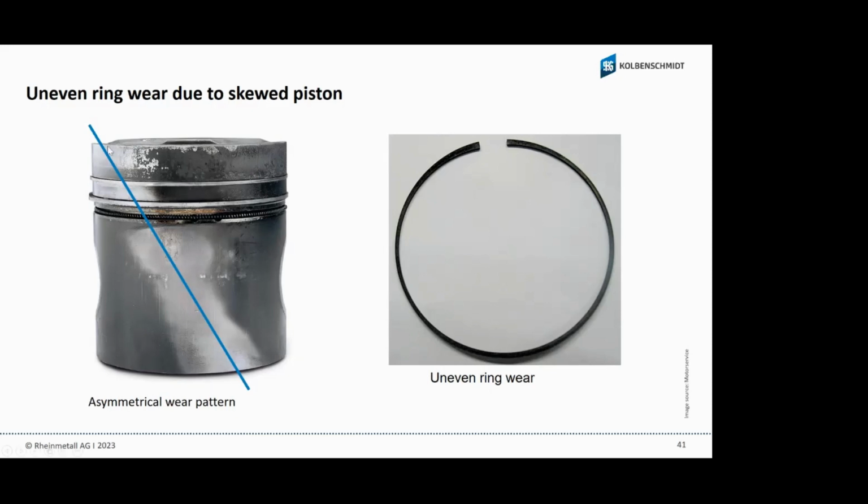You see it also when a conrod is bent or something is wrong, so that the piston doesn't run perfectly in line with the bore. Then you see marks on the piston itself, and then you must check the conrod. Sometimes the customer doesn't say exactly what was before this fault in the engine.